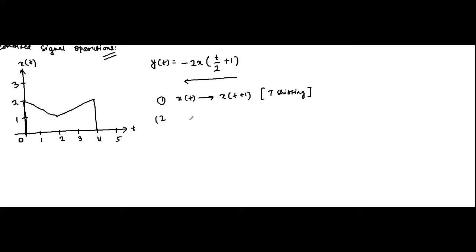Then the second step, performing time scaling to convert x(t + 1) to x(t/2 + 1). This is time scaling.